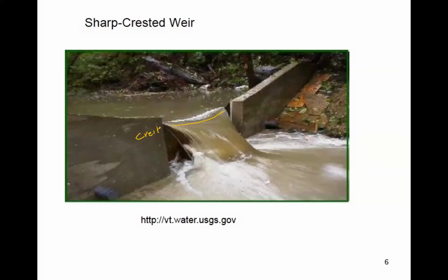And the flow becomes critical at the crest and then supercritical downstream. Write it down. This is clearly supercritical flow. Might be for different reasons. These relatively smaller weirs, this looks like maybe less than half a meter tall or something like that. These could be for different purposes, usually for eco-habitat environmental reasons, like you want some ponding upstream for species that use this, for different reasons, or fish or frogs or other creatures.